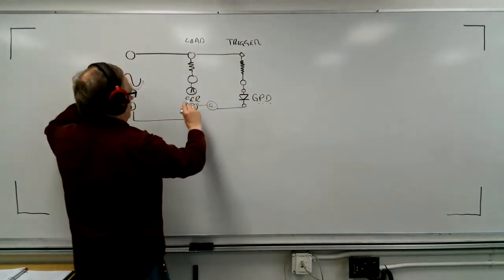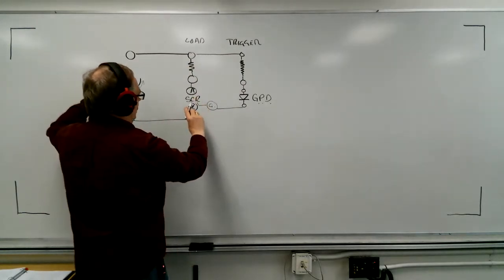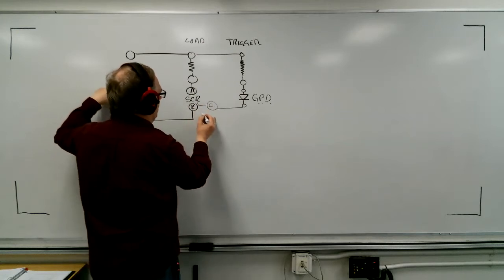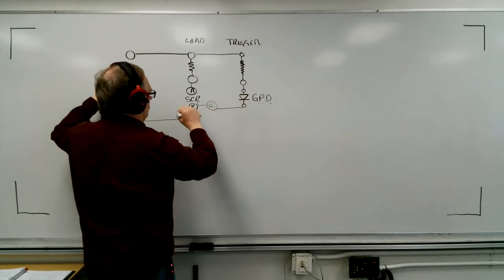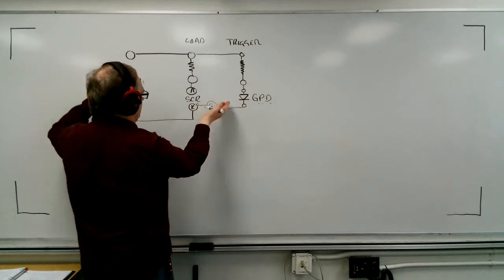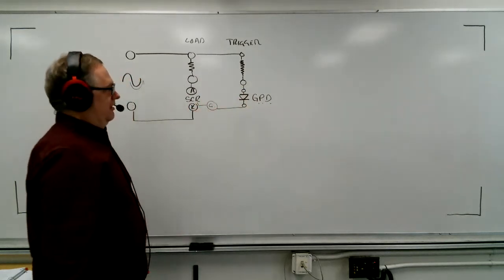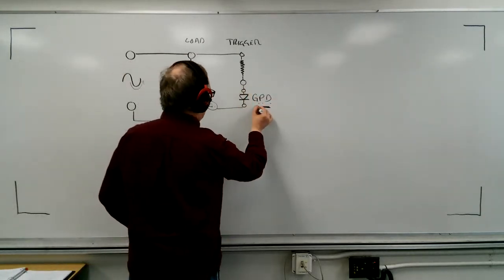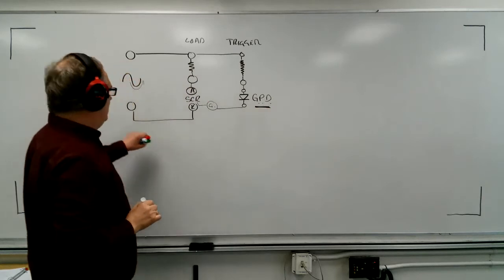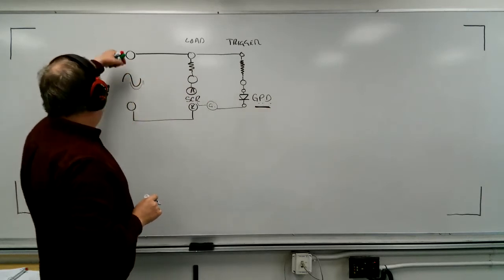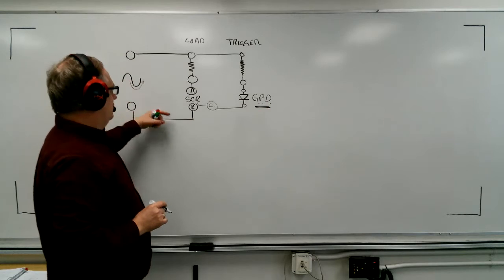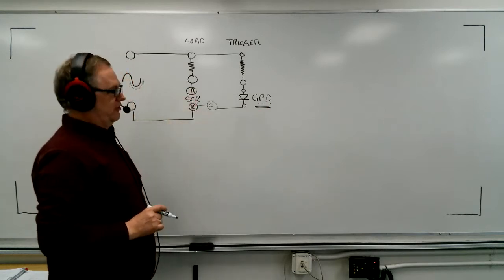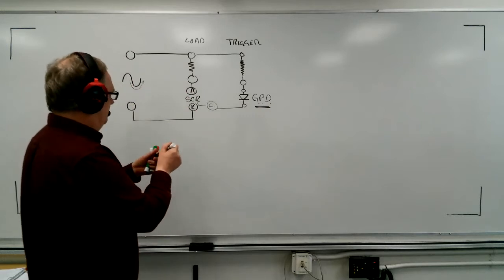The cathode to anode is able to block perfectly. But remember, the reverse voltage rating of the gate is very low. Without this diode, it would allow too much current to flow through and destroy the SCR. So this gate protection diode is necessary mainly because when the AC reverses, it will push back against it and try to push reverse current through the gate.